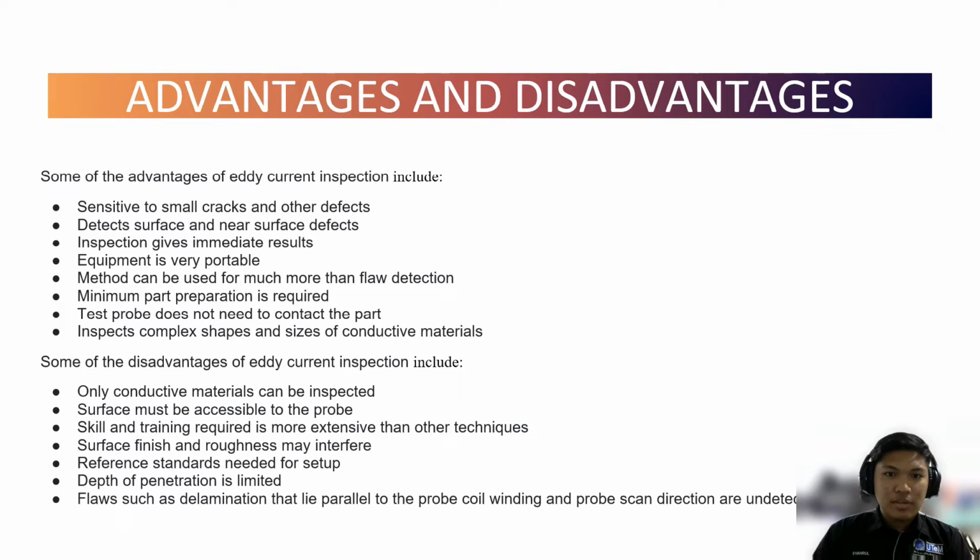Reference standards are needed for setup. Depth of penetration is limited, and lastly, flaws such as delamination that lie parallel to the probe coil and probe scan direction are undetectable.